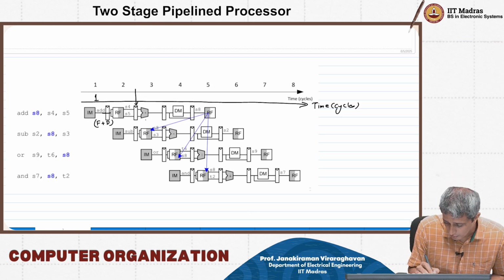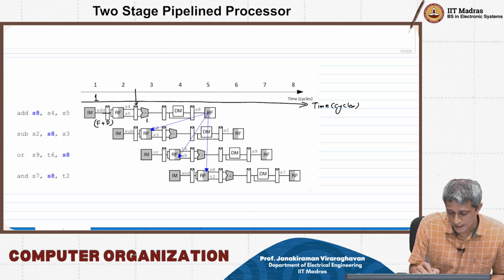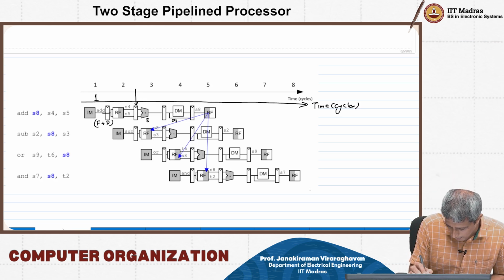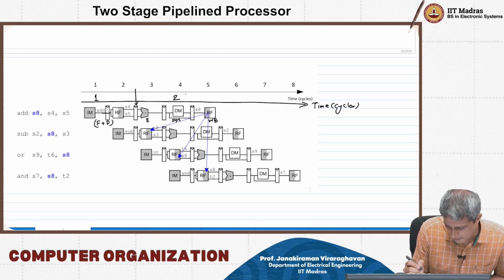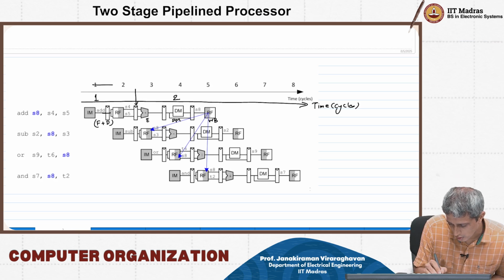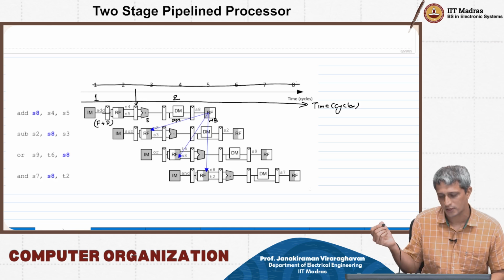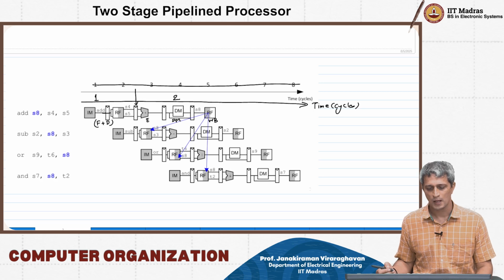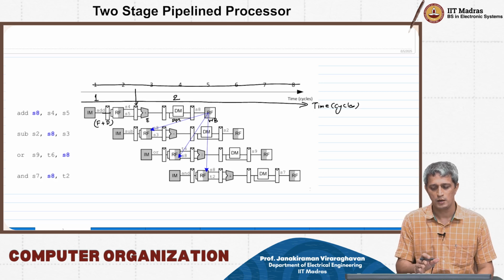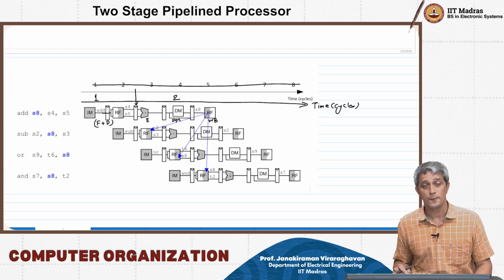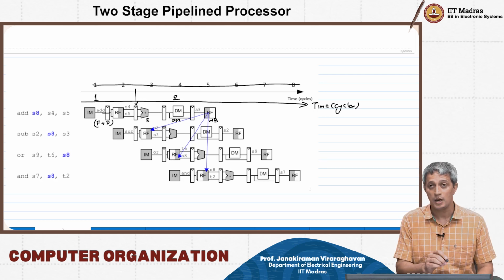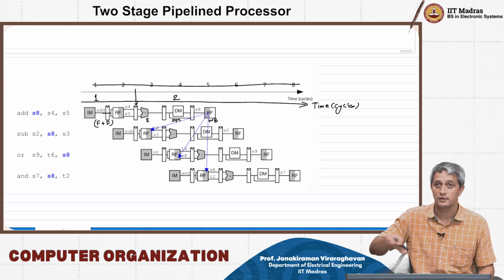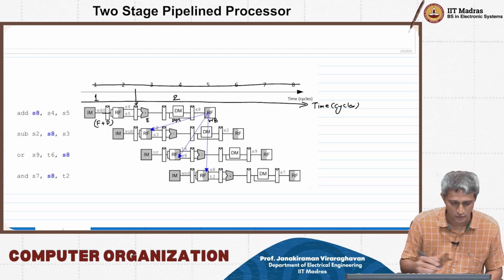Okay, and here we are talking about execute, data memory and write back in the second clock cycle. So technically this is my second clock cycle. So this doesn't exist anymore because that is for the 5-stage pipeline. My clock cycle is 1, 2. Okay, and where do the other instructions happen? Well, that has to get offset significantly. So we will have to draw this again.